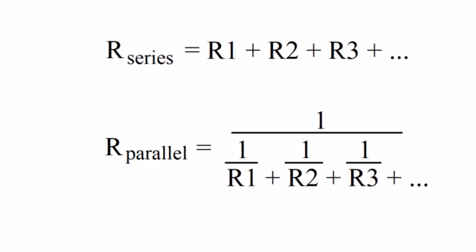That's probably too small. 14.3 microfarads, 70 microfarads, which it can't be. That's bigger than even the biggest microfarad that's being used, and 1,000 microfarads. So the answer choice is B, 14.3 microfarads. Now you can do the math, but you can just look at the answer choices and know that that's going to be the right one, because it's less than the smallest value of capacitor that's used, but not incredibly smaller.